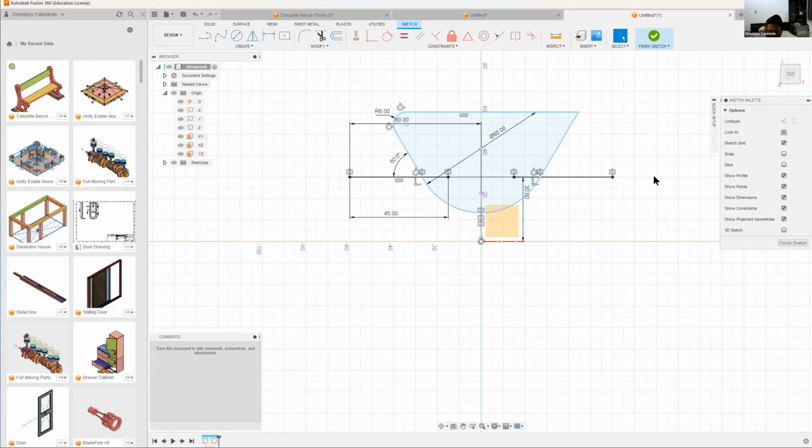So that's my fillet. I can do the same thing on this side. I can say create fillet. I can pick this one and this one, and I say I want it to be 6 millimeters and create the fillet. So I don't need to go through that rigmarole of creating a circle and then going through all of those things. So these are sketches in 2 dimensions.